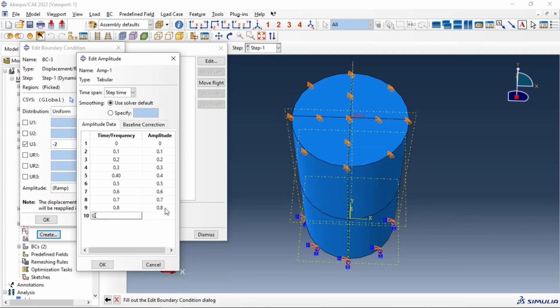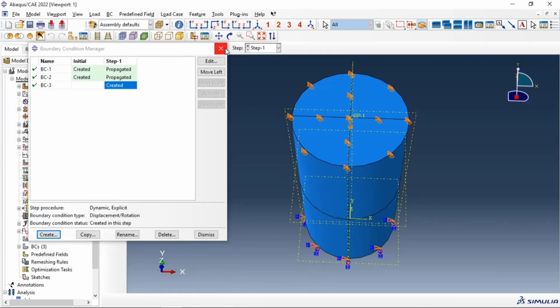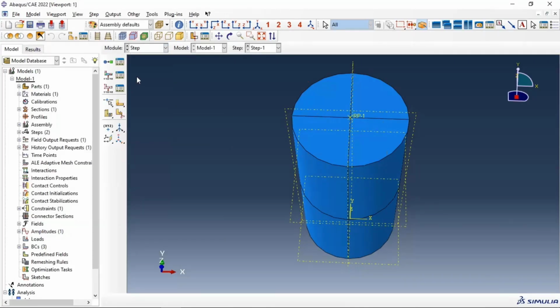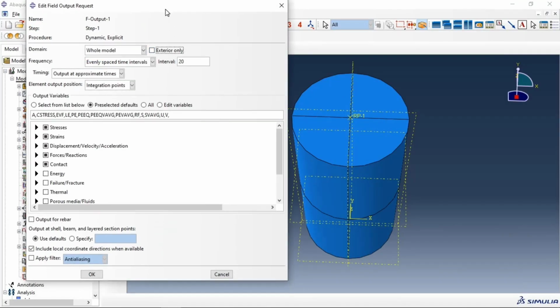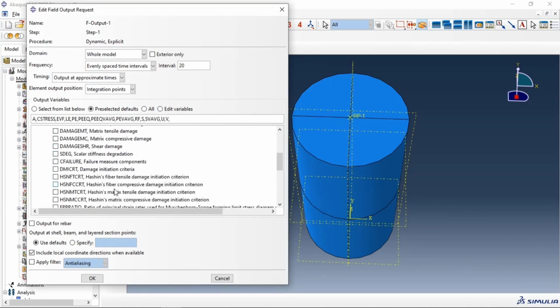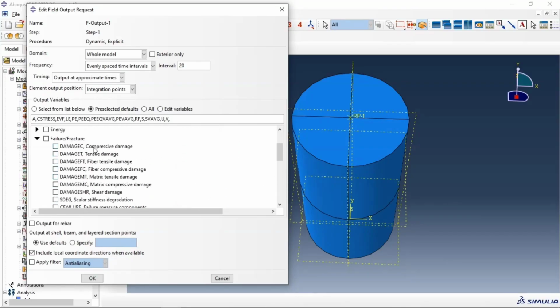As you can see, the CDP, or the concrete damage plasticity model, has been defined by using dilation angle, flow potential eccentricity, K ratio, and viscosity parameters, and obviously Young's modulus and Poisson's ratio. The first property I mentioned was the elastic behavior. As the load gets applied on the cylinder, we need to accurately capture the behavior of the concrete. So in that process, we go with the elastic behavior, and then we will get to the plasticity behavior.